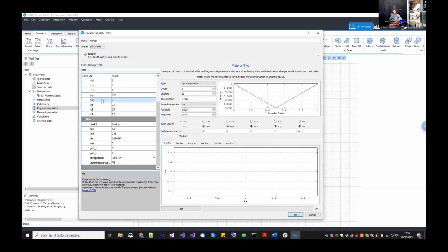You cannot use that fine mesh, so you can use something like one element for each brick, and the mortar will be a thin layer with its thickness of 10, and then the other dimension, which will be very large. And it is fine that OpenSees takes the minimum length, because in micromodeling, the crack will always be in the orthogonal direction of the thickness of the mortar joint. So the regularization will be perfect in that case. Okay, so just keep in mind that in OpenSees, the characteristic length is the minimum size of the element edges.